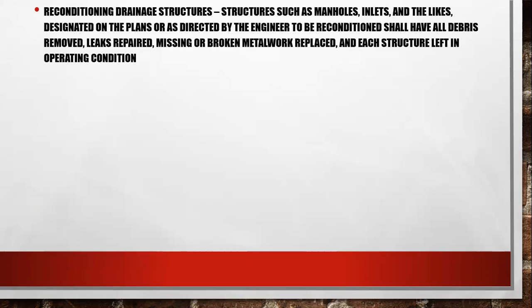Next is the removal of drainage structures such as manholes and inlets, as designated on the plan or directed by the engineer. All debris shall be removed, leaks repaired, missing or broken metal replaced, and each structure left in operating condition.